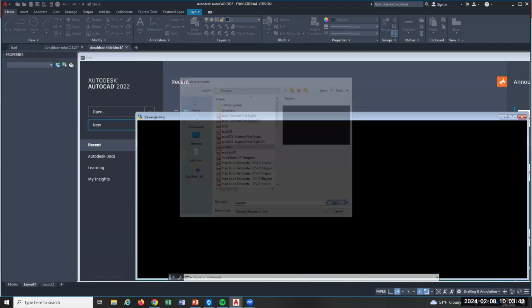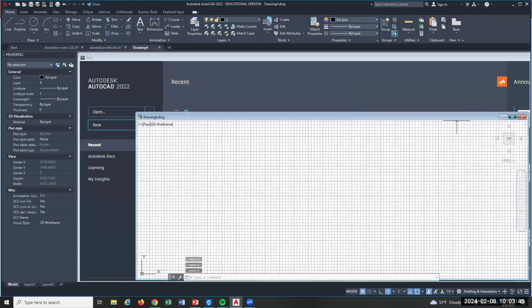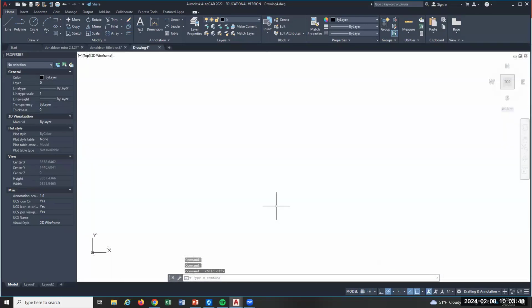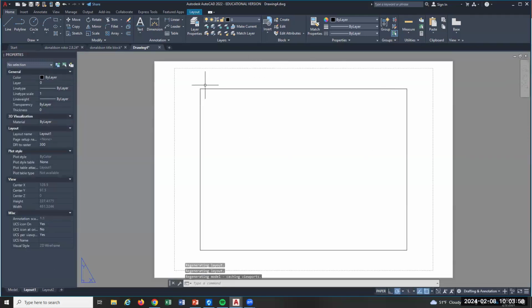And when you open that, wait, there we go. It looks the same. Even the grid looks the same. I turned the grid off. But yeah, it's hard to tell that this is anything different. There are some subtle changes when you go into layout. The paper size is very strange. It's a metric size piece of paper. It's kind of odd, right? So in metric, when you go into layout, you should set that to a normal piece of paper because most of our copiers are not going to understand this piece of paper. And I'll show you how to do that.